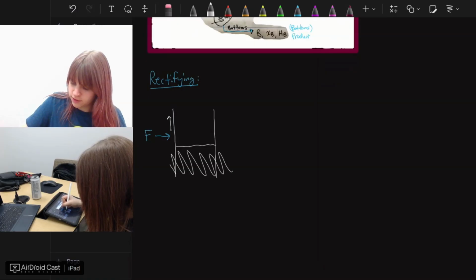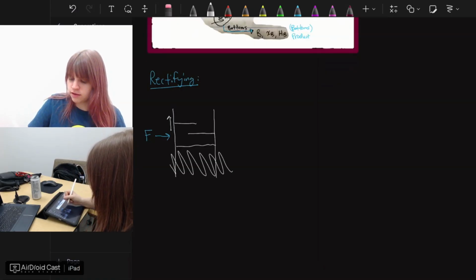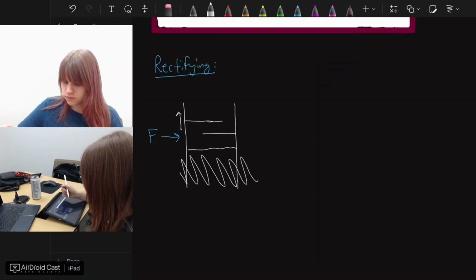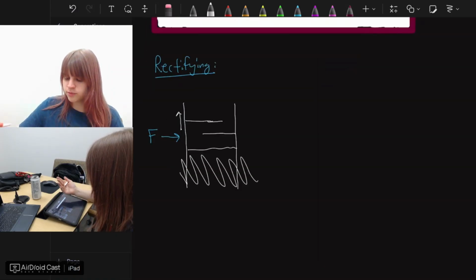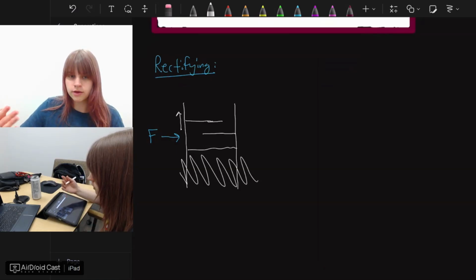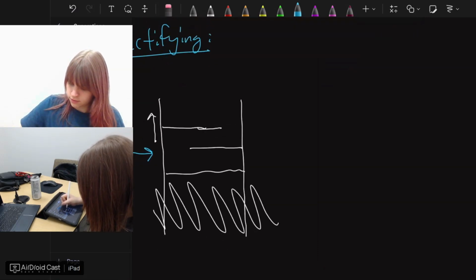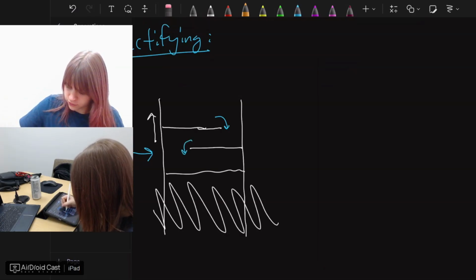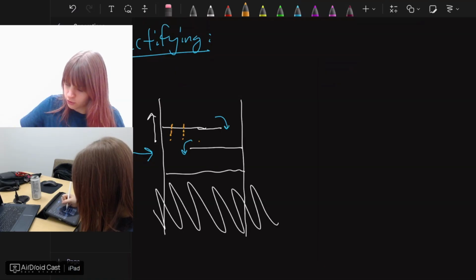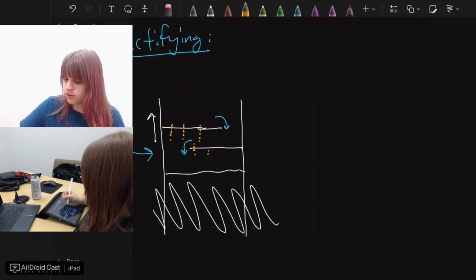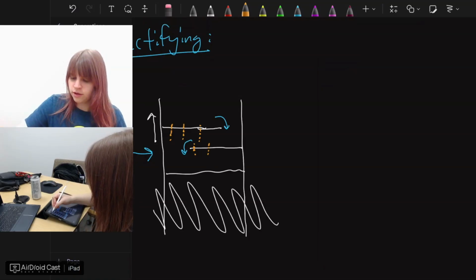What you typically have in a distillation column are trays. These trays allow for optimum heat and mass transfer, so the liquid overflows down and the little gas bubbles rise, typically through holes, depending on how your trays are set up. But it looks something like that. I'm just going to get rid of that for now to simplify this diagram.